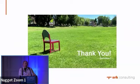We take that unit drain-down curve and multiply it by the surface area that is representing that particular height, that particular zone in the heap leach. There are many different zones, 10 of them in this case. So it's something like 80-odd columns that we had to calculate that way.